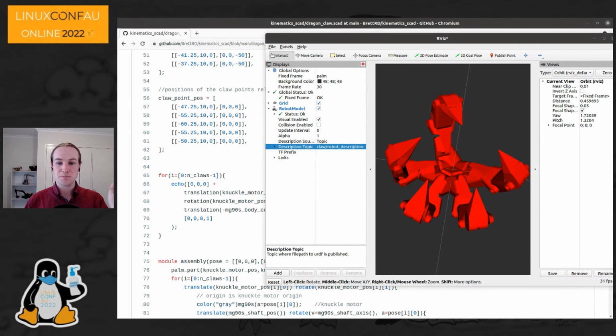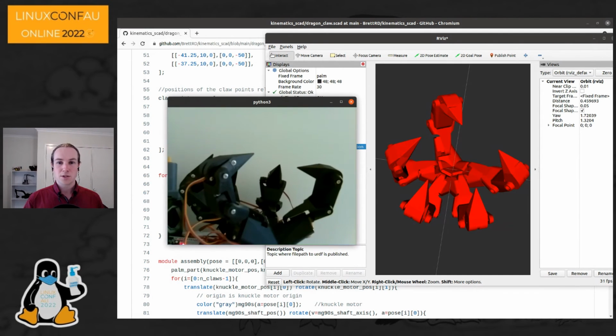But vacuum cleaners have a little spinny LiDAR that just does a 2D scan. Those produce a fairly modest amount of data, so you can attach those to a microcontroller and then spool all of the ranges and angles out to a host system, or deal with them on the local device.